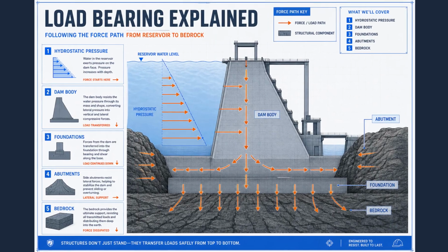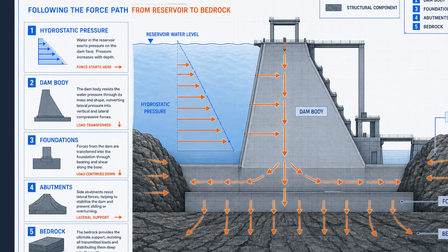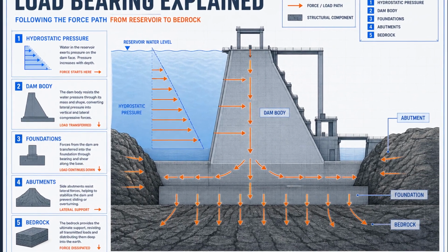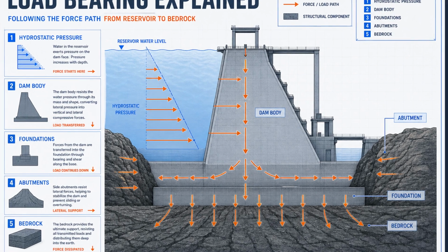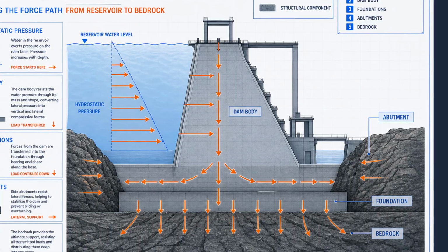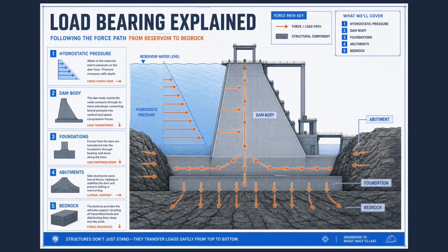Water pressure pushes the upstream face. The dam redirects that force into weight, geometry, and foundation reactions. Spillways manage extremes, drains manage uplift, and monitoring validates behavior. That is how a static wall becomes a dynamic safety system.